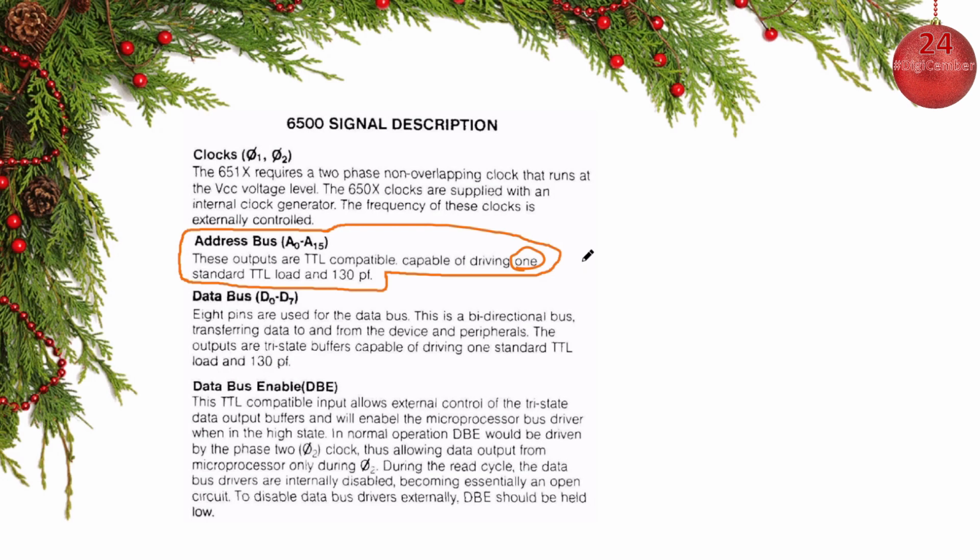And that could prove to be a problem. So of course we can solve this by just using a buffer, as we know from the theory from before, because the address bus is only one direction. That will solve this problem. We can use a buffer chip with 3-state also if we want to disconnect the address bus.